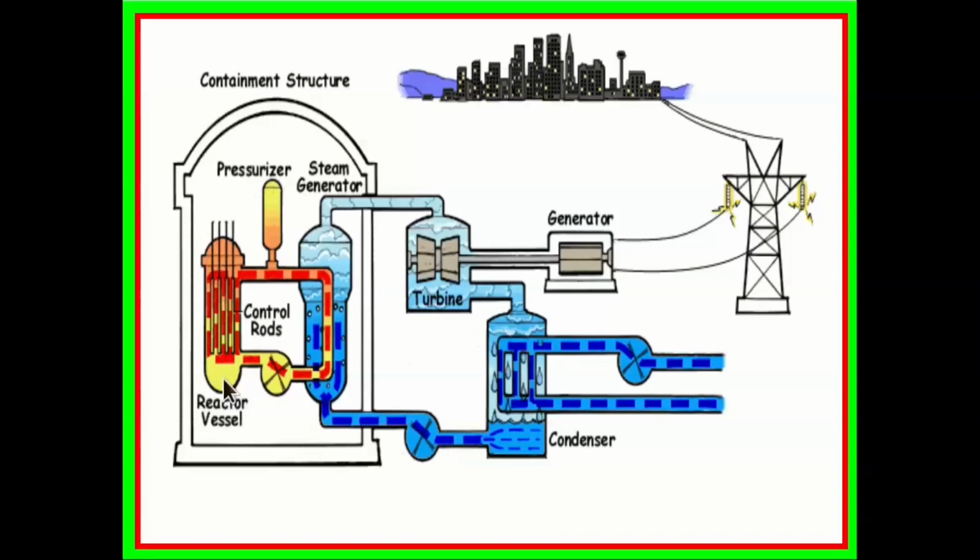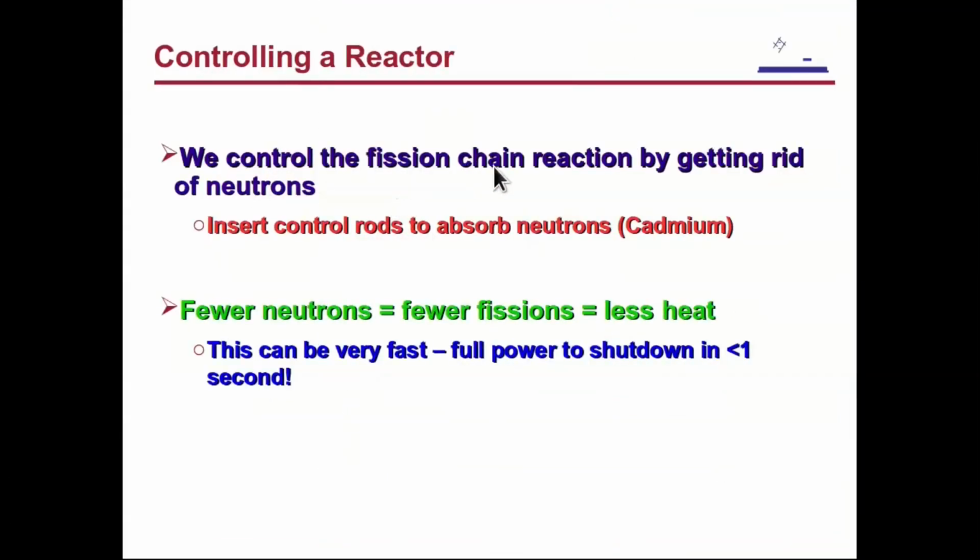We have the reactor vessel, we have the fuel, uranium for example, and then initially a starting neutron will be released in the system. So that will start the chain reaction, and heat is produced because of the large number of fission processes. Then the heat is applied to water, which is heated up and converted to steam, and the steam drives the blades of the turbine. In turn, the shaft of the turbine is connected to the shaft of the generator. The rotor rotates inside the stator coils, and that induces the electric current, which is then distributed to the power grid.